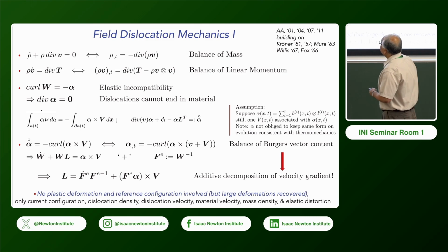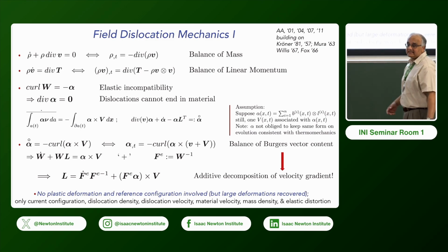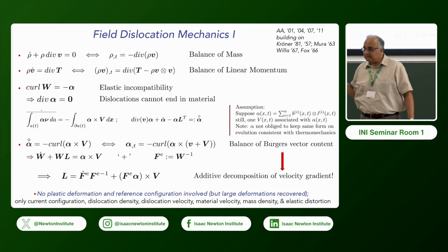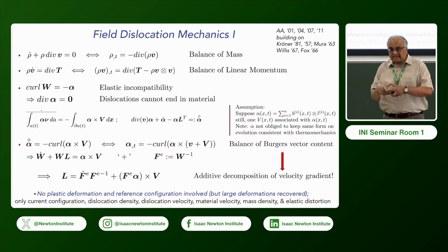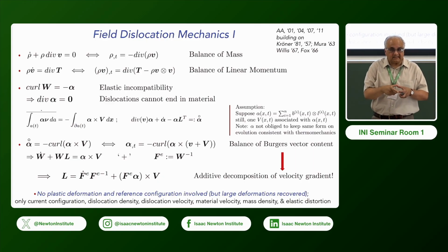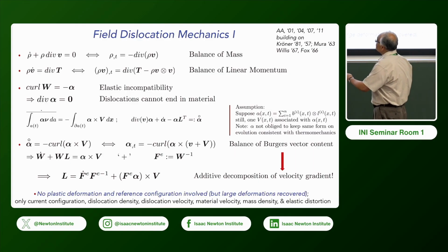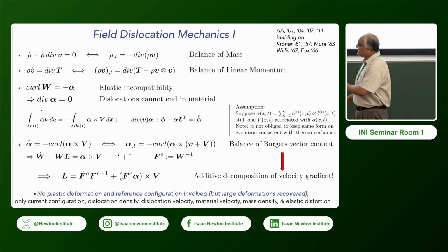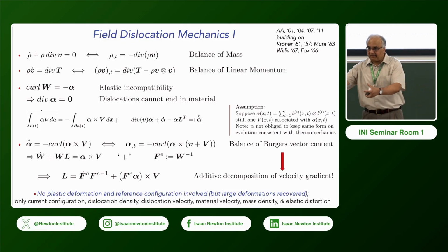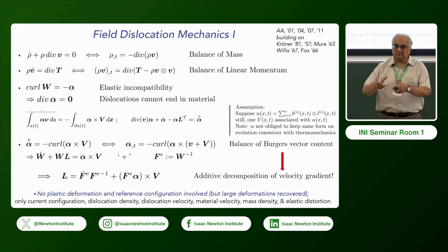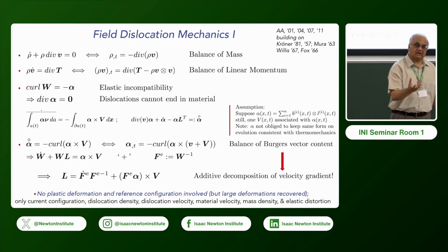to boundary. Now, for this thing, for those who like the fancy, this is a vector valued 2-form. So it's something that lives on areas. It's a density on areas. So then if you do a balance law or a conservation law, this is the Burgers vector content in any deforming area patch. So alpha acting on nu, the normal to the patch, gives you the Burgers vector content.